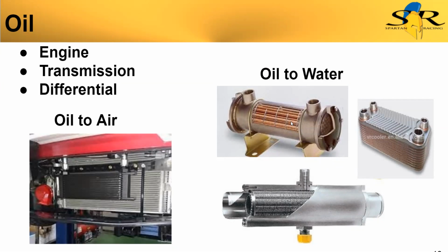So you can put this, it's smaller, and you can put it closer to the engine or mount it in some obscure place. The downside is that if there's a failure of this oil to water heat exchanger, you may have oil and water mixing, and that's bad for both your cooling system and your lubrication system. But yes, oil does flow through these. Like I said, it's pumped out of the engine, goes through the cooler, and then is fed back into the engine.